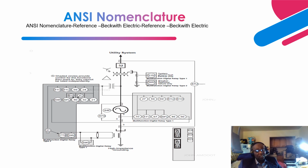Next is loss of excitation, and this is an impedance-based protective relay measurement, based on the magnetic field on the rotor. If there is a fault on the rotor, or there's a fault somewhere in the stator, this relay detects the change in the magnetic field based on changing impedance, and it's able to trip the required breaker.